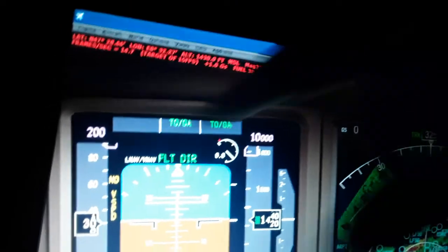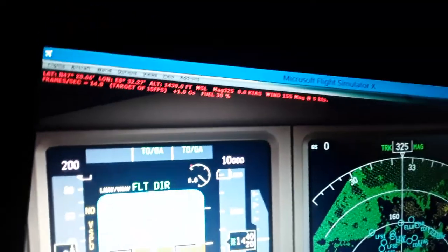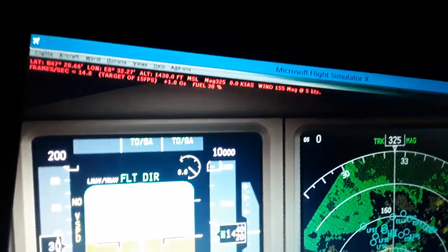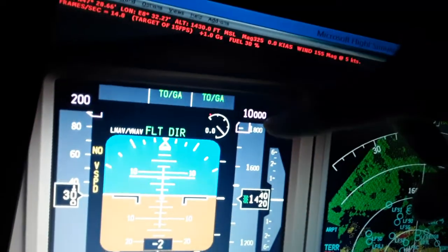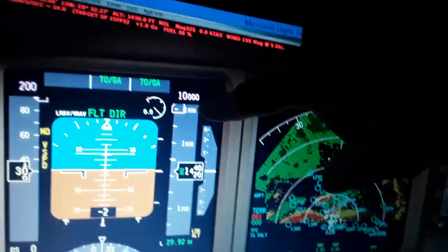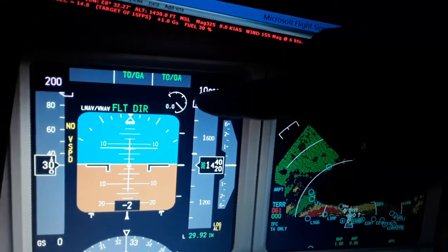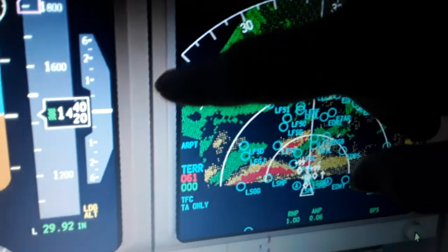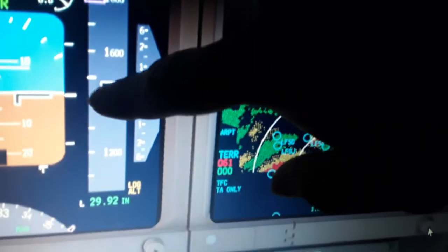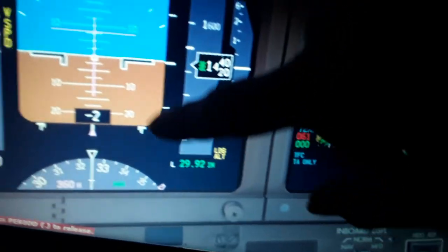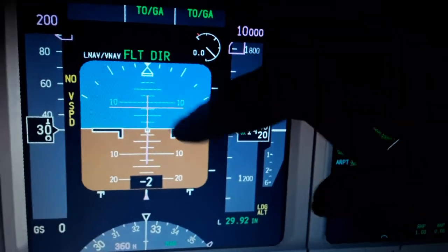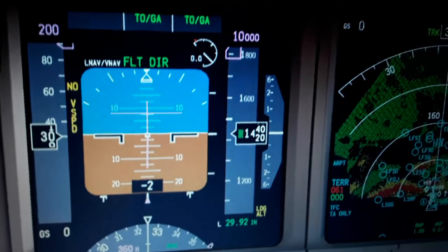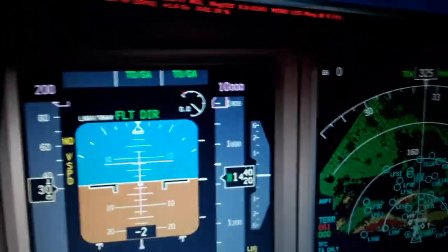primary flight display, the airspeed selected and the altitude selected from the autopilot flight director system, the takeoff go-around mode. Here's the flight mode annunciator, the altitude selected from the autopilot flight director system, and the vertical rate of climb and descent tape, this tape over here. So you can see the barometric pressure, you can see the pitch ladder in degrees, the angle of attack of the aircraft, and the horizontal and vertical altitude.